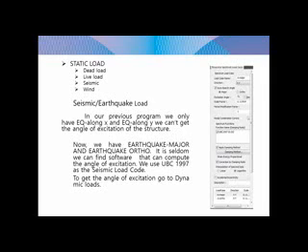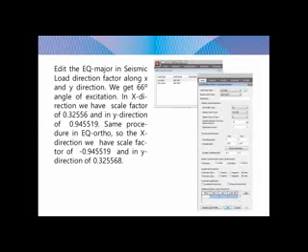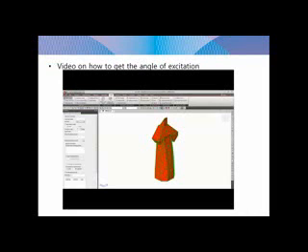Showing this in the video also. First, we go to the load, then static. Go to type earthquake, major, and then type is earthquake, then add. And then earthquake ortho, same, also add. And then go to the dynamic load, then the response spectrum function. We use UBC 1997. Change all the parameters based on your design criteria. Then press OK.